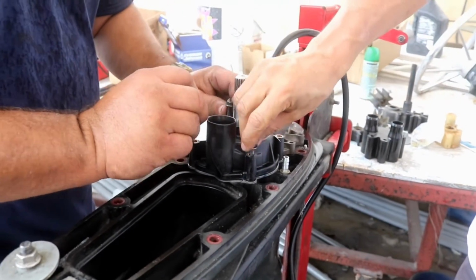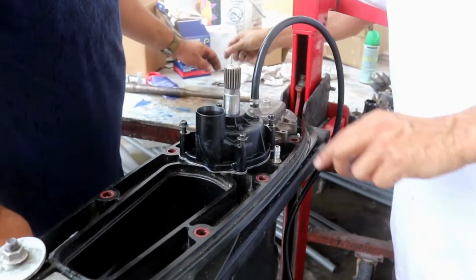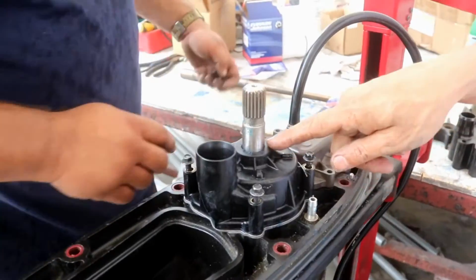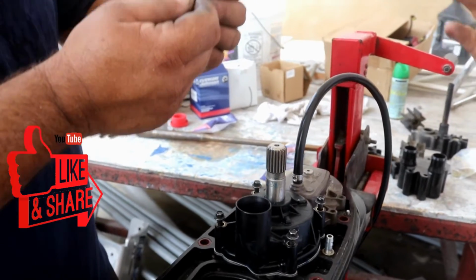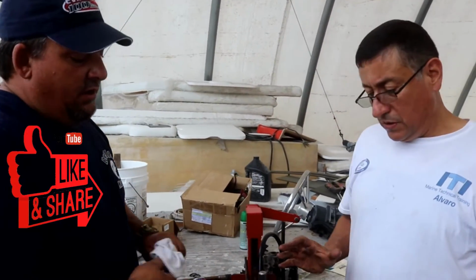Put the bolts and apply the torque in diagonal. Correct. And what about the O-ring on top? This one actually has it inside, okay? And then the O-ring that's on the shaft will actually go in here in the tube. In the tubes, okay. And you have to put grease on these as well. In both of them. That's simple. That's the process. Yep, that's the process on this particular outboard.